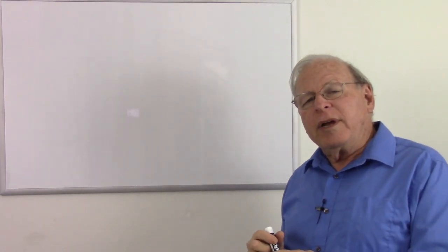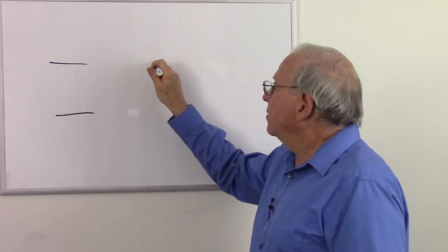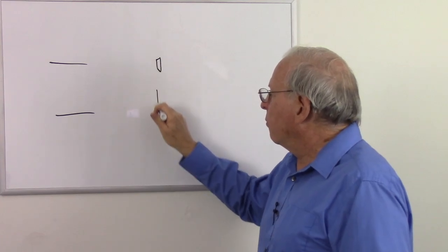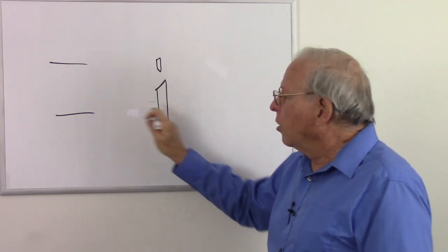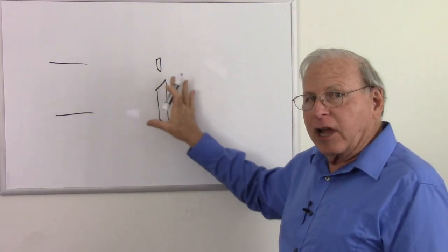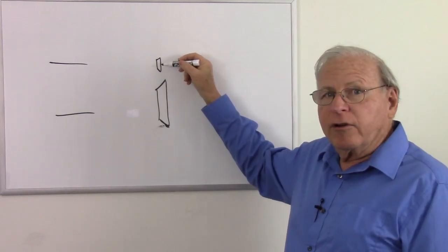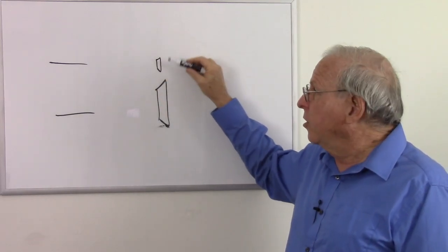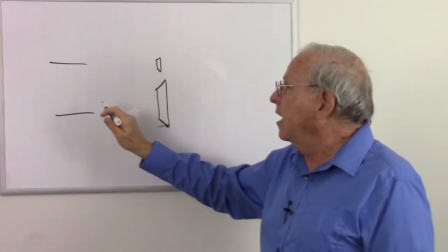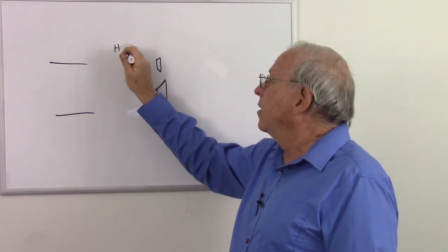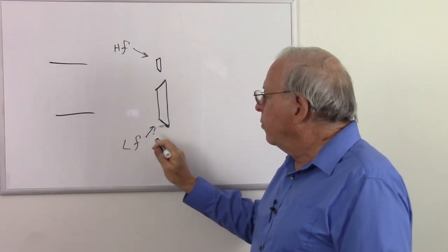So when we have the output from the audio amplifier, we want to go, well, here's our tweeter, a little speaker, and here's our woofer, a bigger speaker. And we want to send our low frequencies to the woofer because it's not going to respond well to high frequencies, it's just going to produce heat. And likewise, the tweeters, we don't want to send low frequencies there because they're going to do the same thing. It's not going to respond well, it's just going to produce heat. So we want to take the high frequencies to the tweeter and the low frequencies to the woofer.